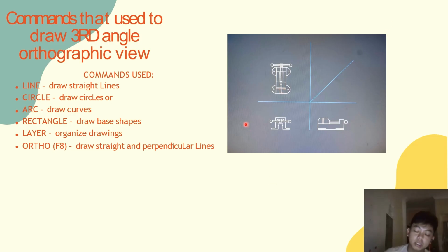First of all, you must start with the box, which is 2.75 width and 7.25 long. And then you can just use circle for this part, for these things that hold the vice down. And then you just project it to the right side and also downward. So that you can do this part here and also this part here.